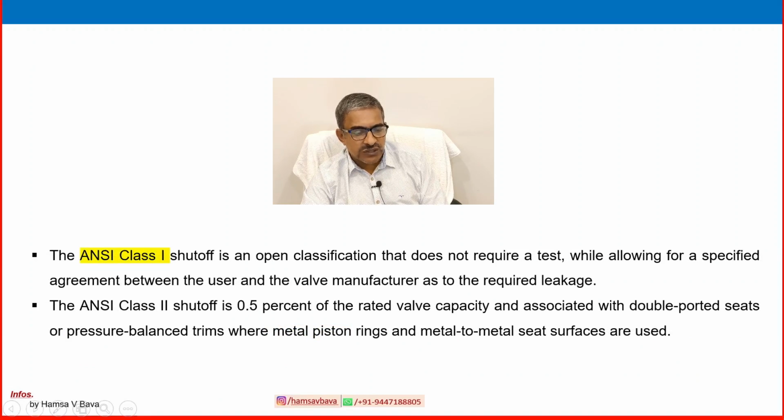The ANSI class 1 shutoff is an open classification that does not require a test, while allowing for a specified agreement between the user and the valve manufacturer as to the required leakage. So, it does not require a test.